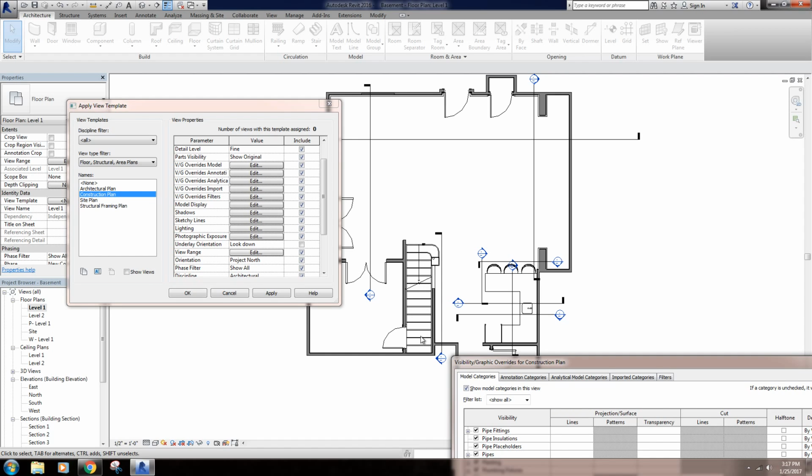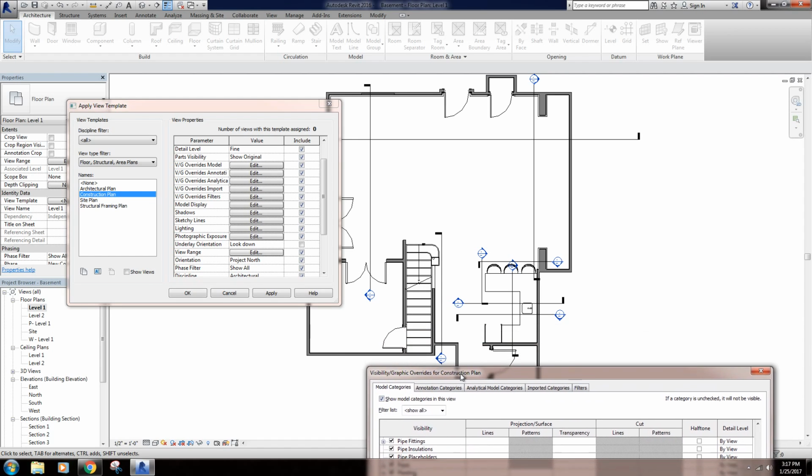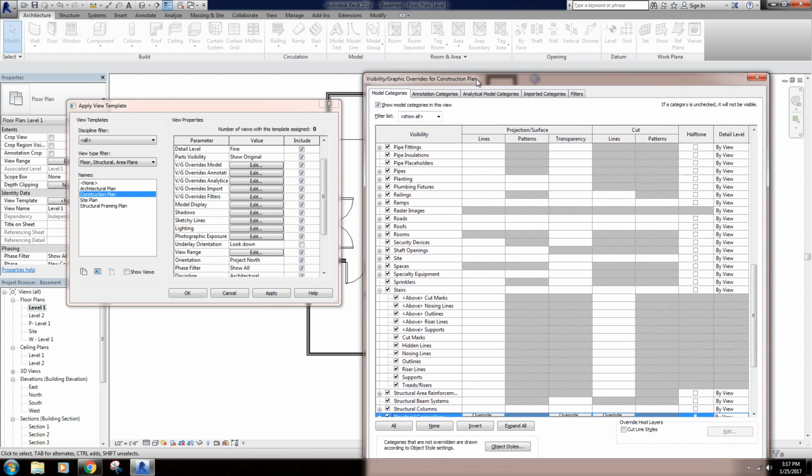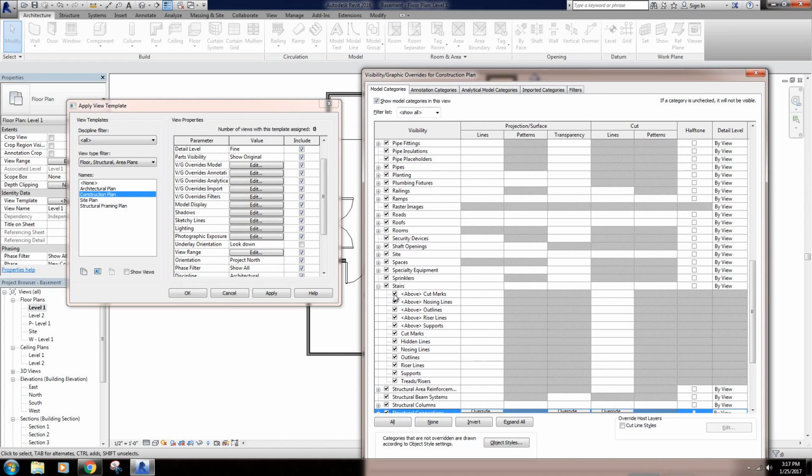But I'm seeing all of these extra treads here, and even though I have a door back here, it looks like I'm opening up right on top of some stairs, but you know there's some storage space underneath that stair, which is what this door is accessing. So we want to show that the stairs are going up. At the break line, they all basically terminate, and then this is a nice clean shown closet here. So all of these things that say above, this is all the stuff that's being shown above the cut mark. So I'm going to turn all of those off.